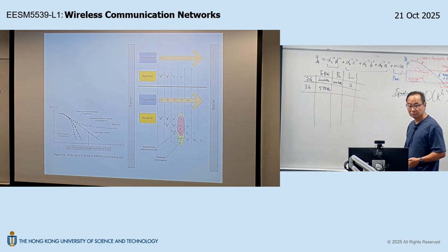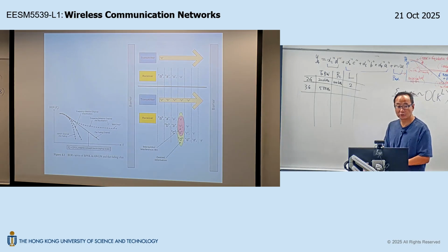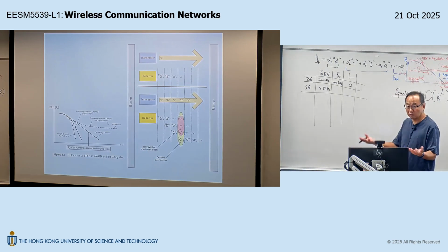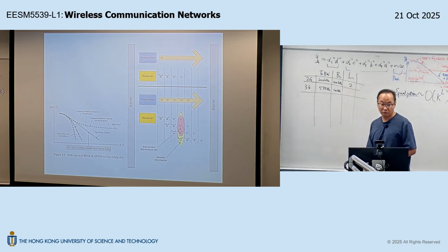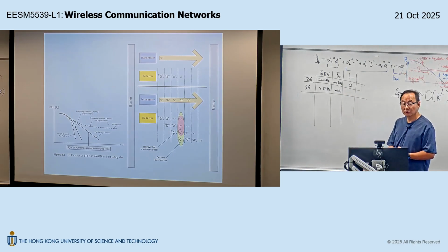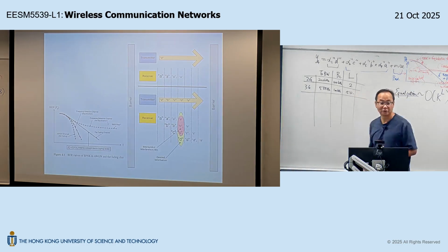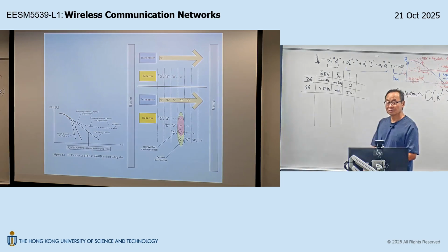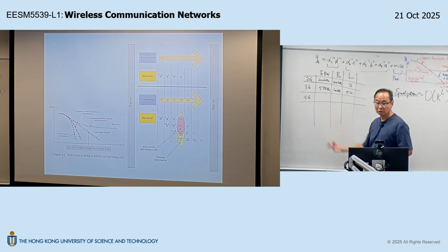Now for 3G, about the operating environment, is there any difference? Not much difference, right? It's also designed for outdoor propagation, outdoor coverage. So the coherence bandwidth, which depends on the operating environment, is more or less similar. Now if you do the math, in this case for 3G systems, the channel memory, we are talking about 50. Okay? Now continue the logic, 4G LTE system.